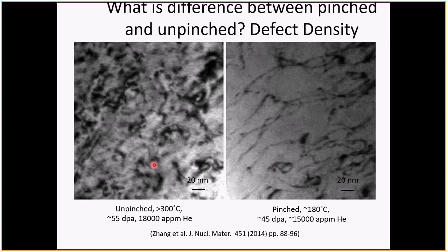Now, the dislocations are already in there from the production, from the fabrication. But in this particular image, if you notice, this side is different from this side. This is very much cleaner than that. And that's because this contains also a large fraction of these little black dots, which are really interstitial clusters, radiation damage. So we have this cluster damage here and very little evidence of it here.